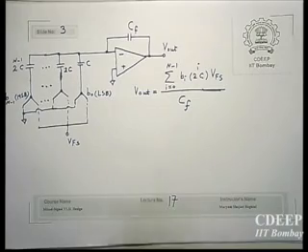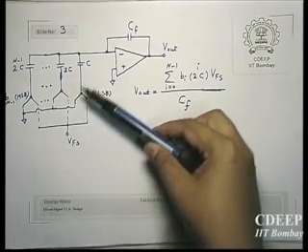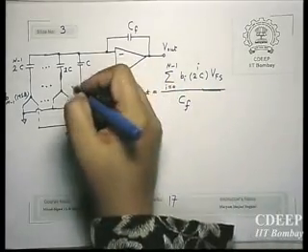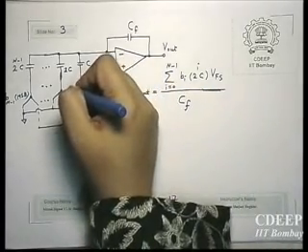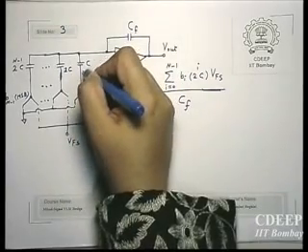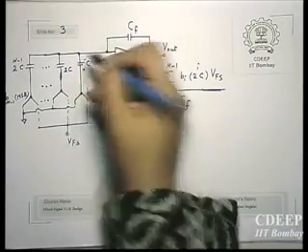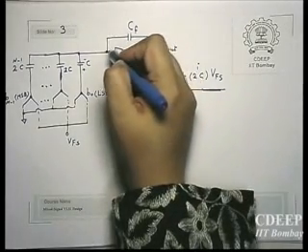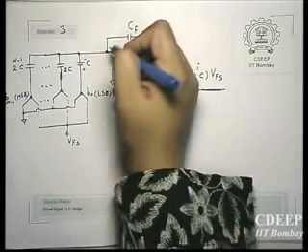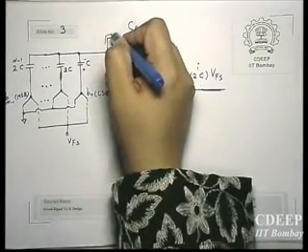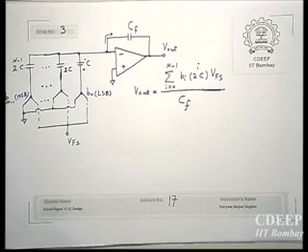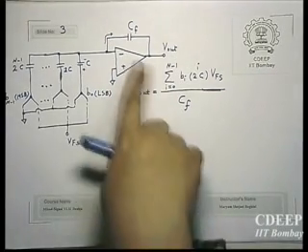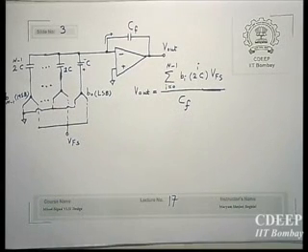Only there is a small point here. You notice when there is a capacitor over here and it's getting charged, charge will get transferred. In fact, this capacitor will get charged in this direction, right? And this charge also will get transferred to the output in the same direction. Therefore, your V out actually may have a negative value if we just assume like this.